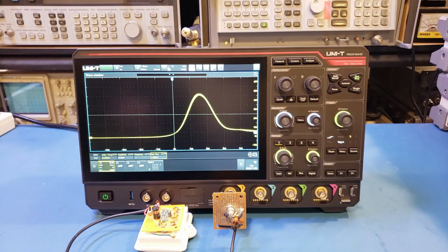Now, a good avalanche pulse generator can probably output pulses much faster than that. So at some point, I may need to tweak the design of the avalanche pulse generator a little bit. In theory, I should be able to reduce the rise time to probably about 300 to 500 picoseconds with better components and probably more careful layout.